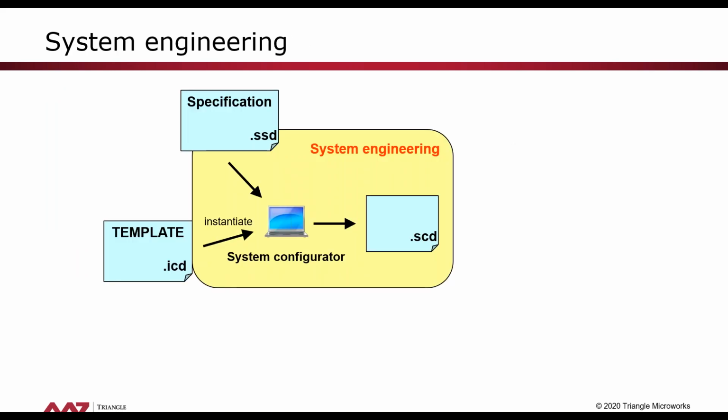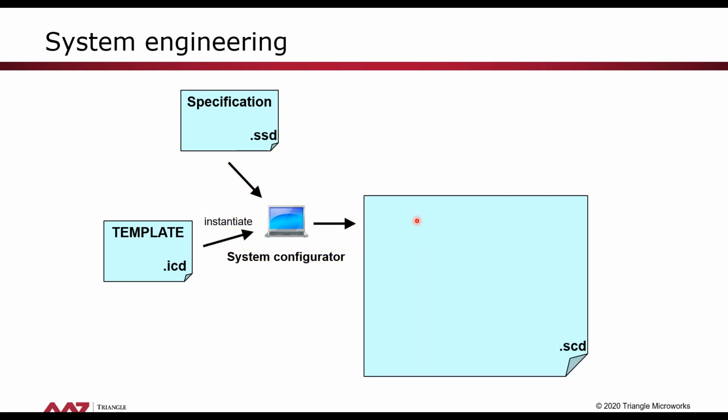What we are doing here is we import the file that we created with the specification, and the ICD file that Joel created, as well as other ICD files for protection for all the devices we need. We import that in the system configuration tool, and then we do the complete design and create at the end what we call the SCD file, the system configuration description file.